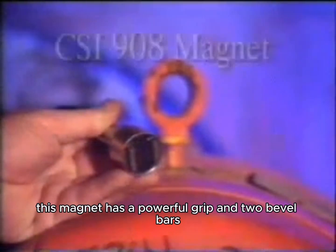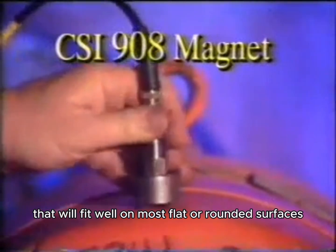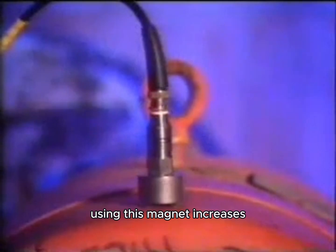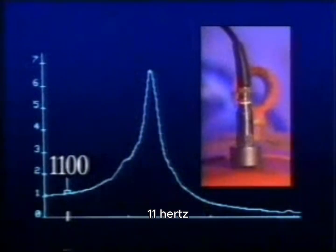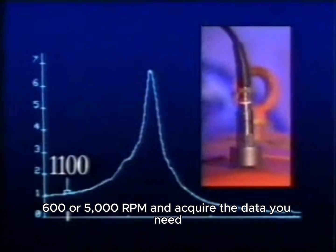This magnet has a powerful grip and two bevel bars or poles that will fit well on most flat or rounded surfaces. Using this magnet increases the linear frequencies of the same accelerometer to 1100 Hertz. Therefore, it can be used acceptably on shaft speeds to 3600 or 5000 RPM and acquire the data you need.